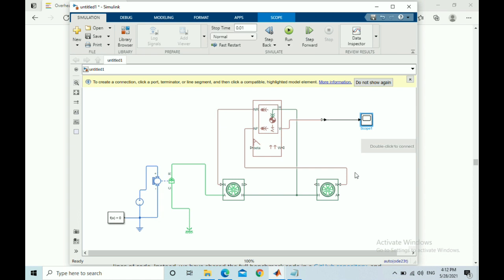Now, more complicated systems are also available all over YouTube. You can connect the motor to a gear, and then connect the gear to the tires. So you can add this if you need, and you can also connect a more complicated DC source, like connecting a PID controller, or they call it a driver in this space. You can give a certain velocity profile to that driver, and it will increase and decrease the voltage to match that velocity profile.